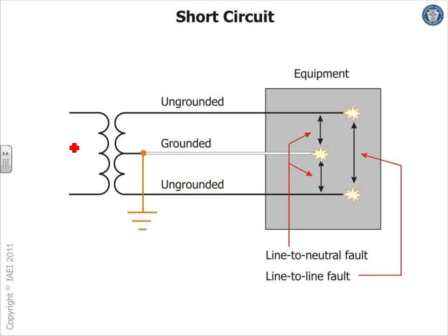So a short circuit is defined as any unintentional contact between any two ungrounded conductors or the grounded conductor. That's how they define it. So you have a phase-to-phase short circuit. How about phase-to-ground? Ground fault. If you have a phase-to-phase short circuit, does the equipment ground conductor play a role? No. You wouldn't see the phase-to-phase. It will sit on the two phases only, be seen by the circuit breaker and trip.